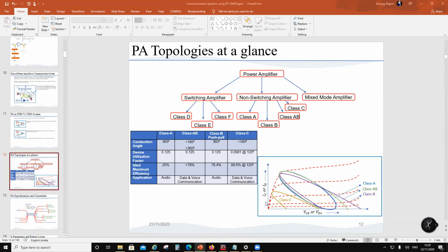Now what is class F? What happens is if you look at a transistor, if you pick up a big transistor, parasitics are going to be more, like the output capacitance is going to be more, the Miller capacitance is going to be more, right? And then the lead inductances would be there. And then there will be losses also in terms of extrinsic resistances and all that, right? So as the transistor becomes bigger and bigger, its parasitics become higher and higher. Now the active power which you can deliver goes on reducing. So it is advisable to use a small transistor to put out power.